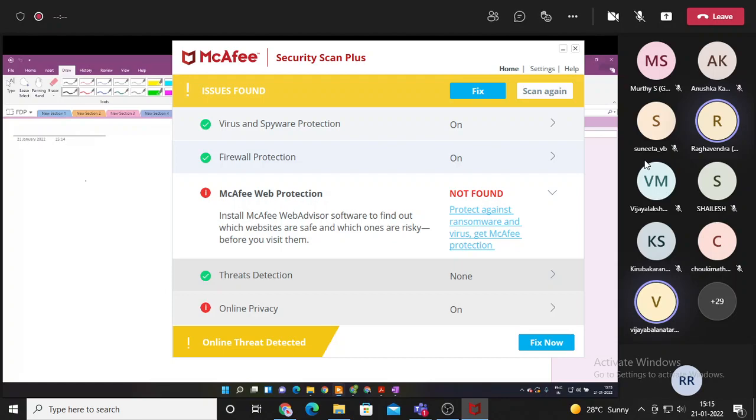In the morning, say I'm using a visual light code in my house, there's a lot of sunlight coming in from the window. Now, in the morning, when I transmit via wave, it will look like this. But at night, when there's no light and I'm using very dim lighting, the wave might go like this. Meaning, there is always a DC offset that is present because of your light sources.